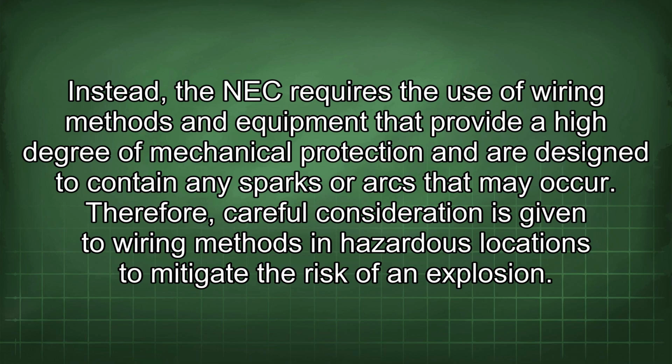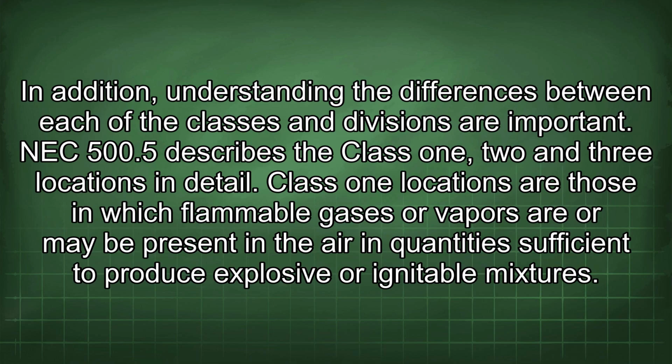Therefore, careful consideration is given to wiring methods in hazardous locations to mitigate the risk of an explosion. In addition, understanding the differences between each of the classes and divisions is important. NEC 500.5 describes the Class 1, 2 and 3 locations in detail.